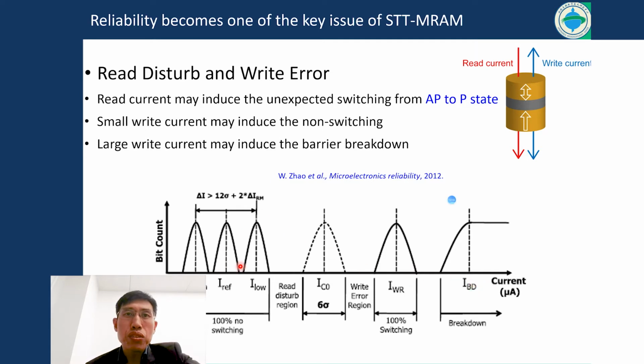So when we use the low current to read it, it's approaching the current to write it. In this case, there are two types of errors: the read disturbance, where the read current will disturb its state, and the write endurance error. So this is why we cannot use STT-MRAM to combine the fast speed and the large lifetime.